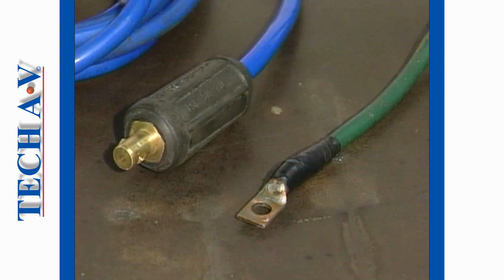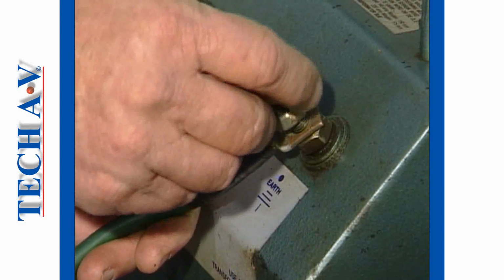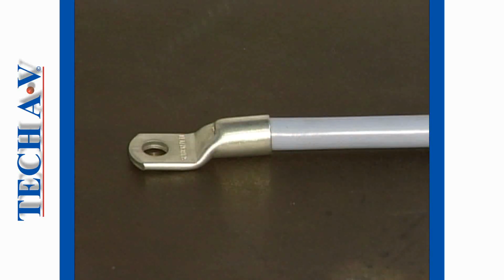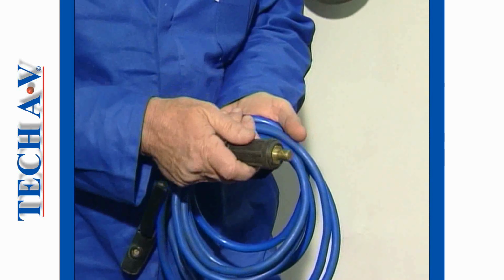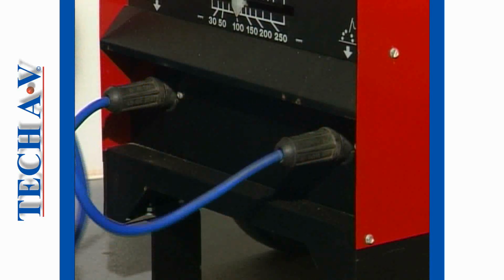Welding leads must be properly terminated using the correct type of terminals. For attaching a lead to a stud, then a suitable lug must be used. Lugs must be soldered or crimped. The machine end of the leads may be fitted with quick couplers that fit into a machine's output connectors.